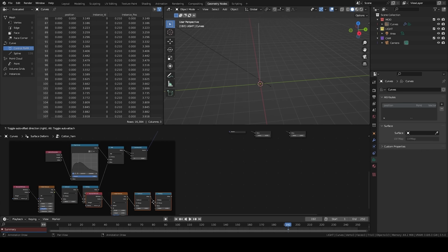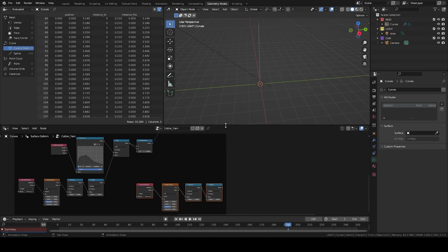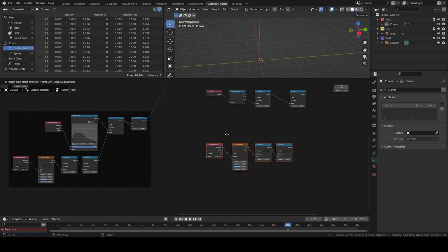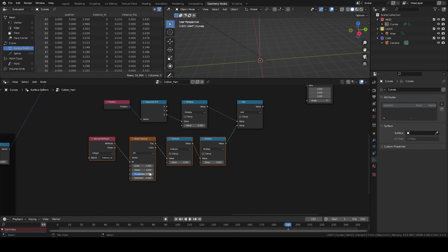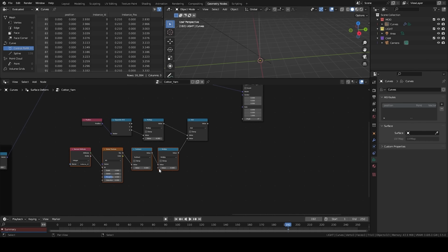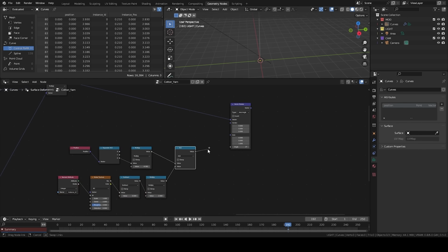If I do Shift D, it's still contained in the backdrop. But if I do Alt P, it takes it out of the backdrop. And I'm going to be able to connect it. We'll also be able to change its scale a little bit. Its amplitude, we're going to be able to let it a little bit stronger too. We're going to put 205 for now, and I'm going to plug it into angle.